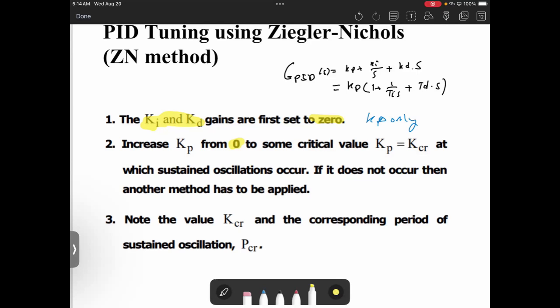Let's recall the root locus or the Routh-Hurwitz criteria. We said that the gain can be increased until reaching the point where what's happening? Marginal stable, right? Do you remember that? When we add the gain, the pole location will be shifted until reaching a gain where it will be marginally stable. So the key is we will try to reach marginal stability.